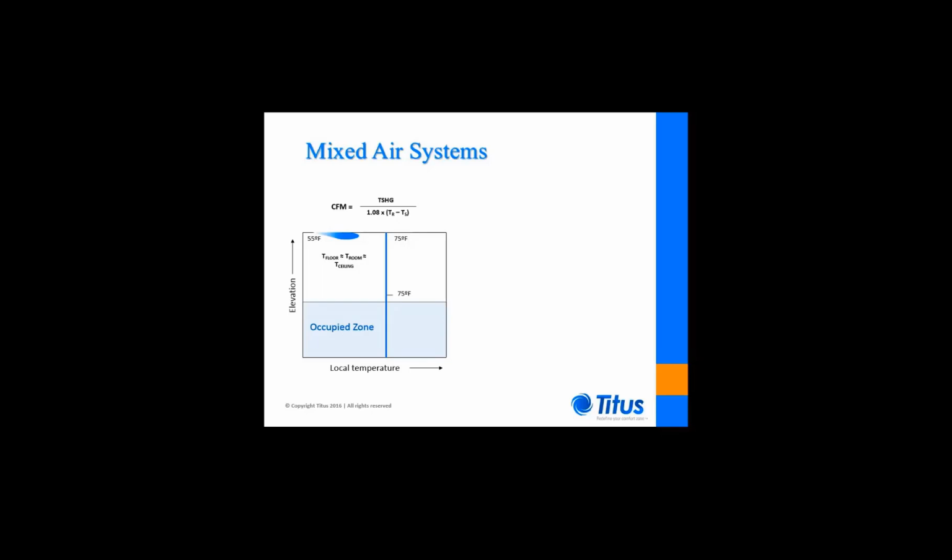We generally consider this delta T to be that between the supply and room air. In the case of mixed air systems, that generally works because the return air temperature is very close to that of the room. This figure relates to the concentration of CO2 in a mixed air system. The term zone ventilation effectiveness relates to the concentration of gaseous contaminants in the return air leaving the room to that at the occupant breathing level. Note that the CO2 concentration in the return air leaving the classroom will always be equal to or less than that at the breathing level of the room.